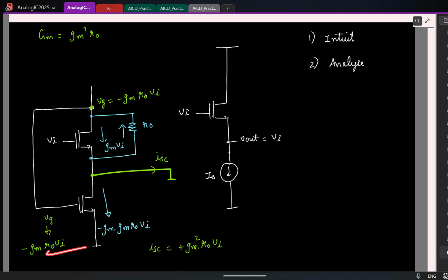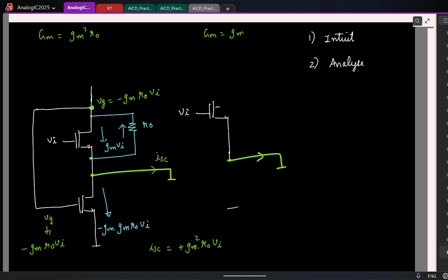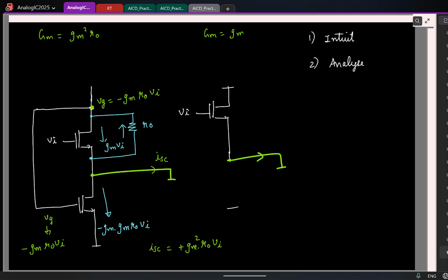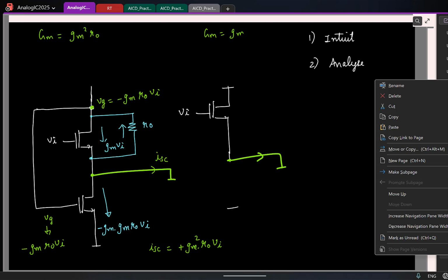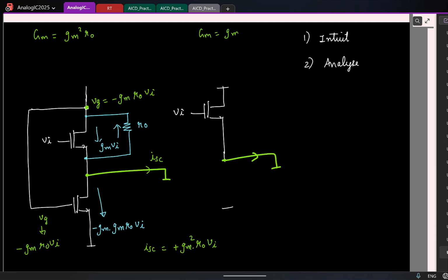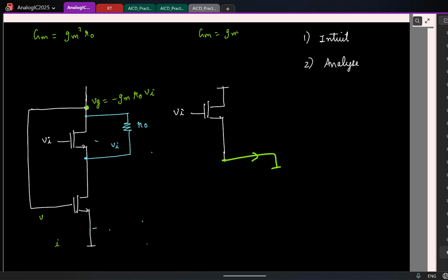So okay, this is short circuit gm for this guy, our plain old common drain. So if I find the short circuit current, I short circuit this. What is the short circuit gm here? Short circuit gm will be the gm of the transistor. Right? So okay, this is a short circuit gm. What should I find next? Rout. So let's do that. So how will I find Rout? Apply a test voltage and find the test current.